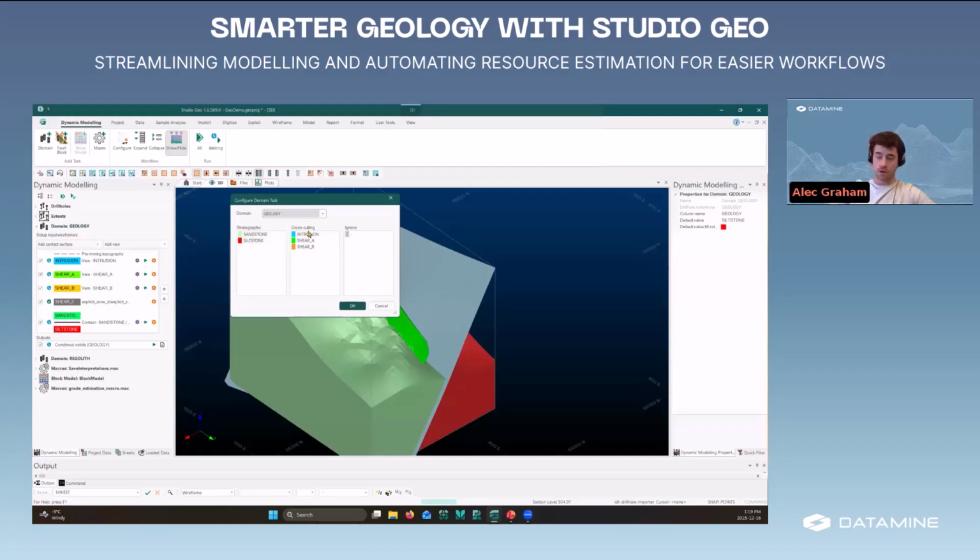Order does matter here. These are youngest to oldest, so that's how they'll be generated. And these two boxes are important as well because in our stratigraphic box, we're going to be generating two-dimensional contact surface wireframes. So in between our sandstone and our siltstone, we're going to create a 2D contact between the two of them. And then in our cross-cutting box over here, these will be generated as 3D closed volumes. So these will be solids.